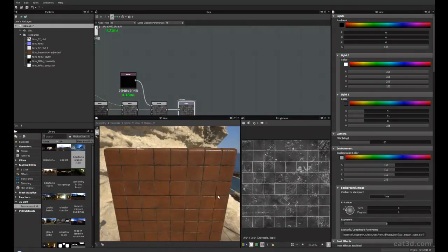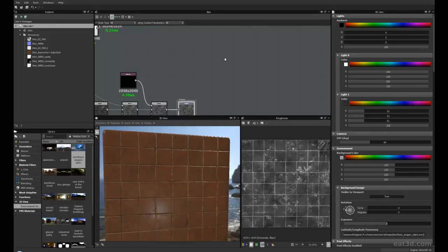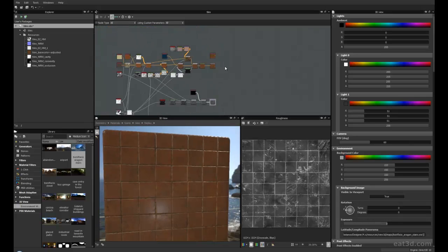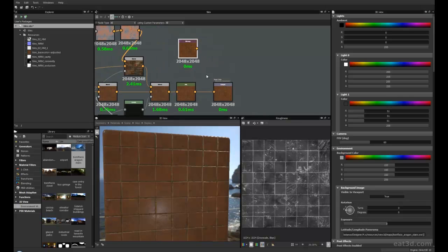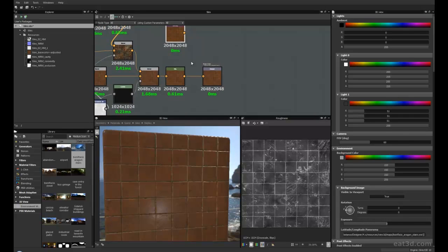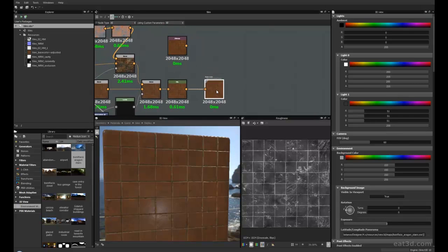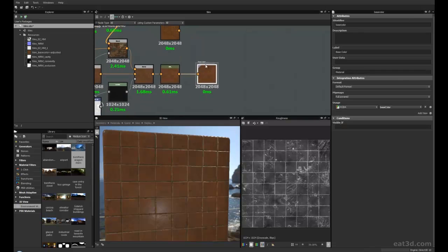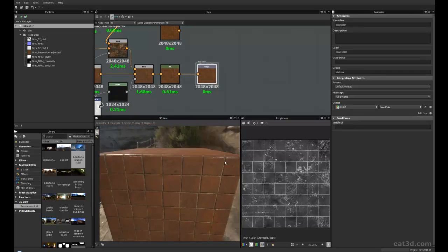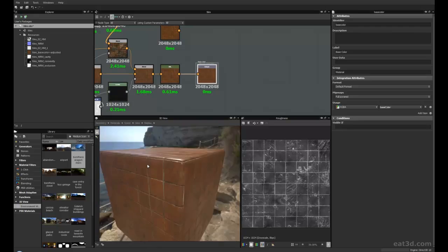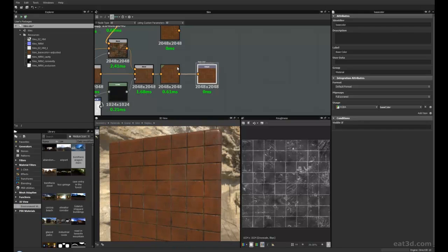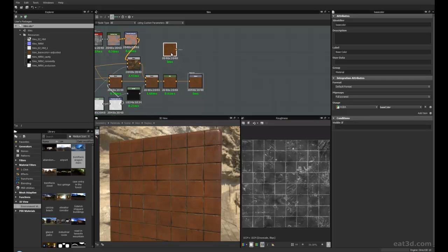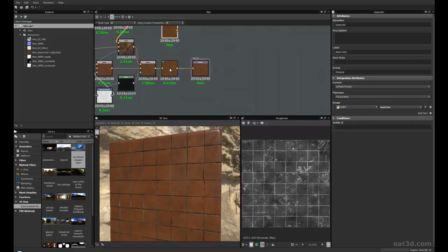But one thing I do like to do is, once I've done all the maps, now you'll see there's a stray node here, okay? And this has been checked. The luminance has been checked in Photoshop. So what I've done is I've completed all the base color. For example, I want to make sure the luminance of the base color is correct. Again, you probably have to read up on some PBR stuff, but you do want to ensure that the actual albedo is not too dark, not too bright. So you need to check the luminance values.